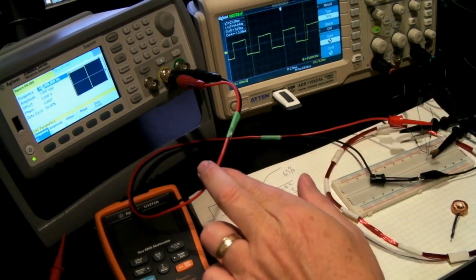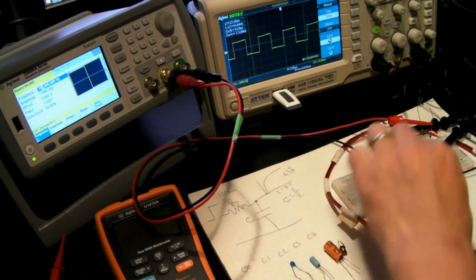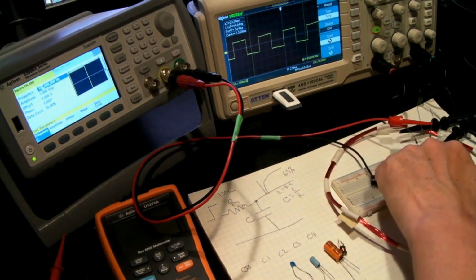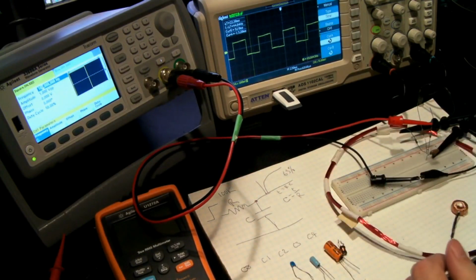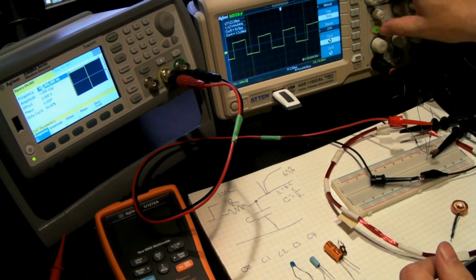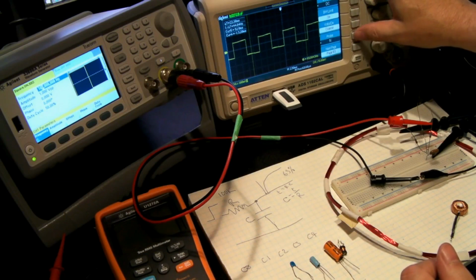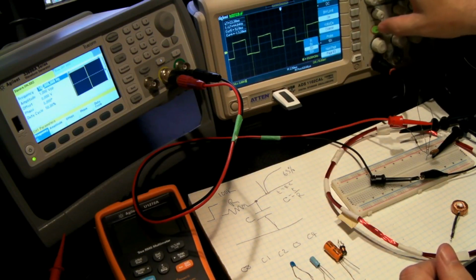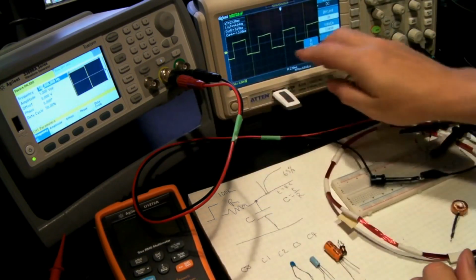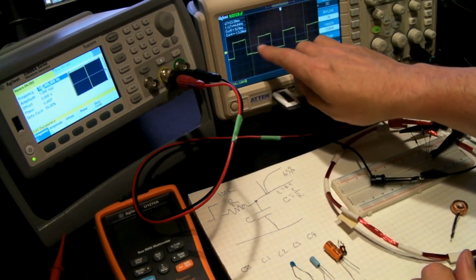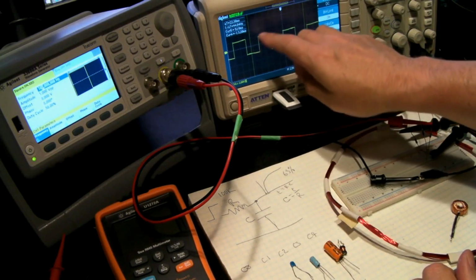I've set my amplitude to 1 volt peak to peak, and I just have the grounds across but not the negative of the capacitor. So on the input to the oscilloscope, I've got it set to times 1. That's why I was getting a funny value. Let's go back to times 10. I've got it set to times 10, so it's 1 volt, and remember I said it's 1 volt peak to peak, so what we've got here is negative 1 volt and then plus, so it's basically 2 volts.